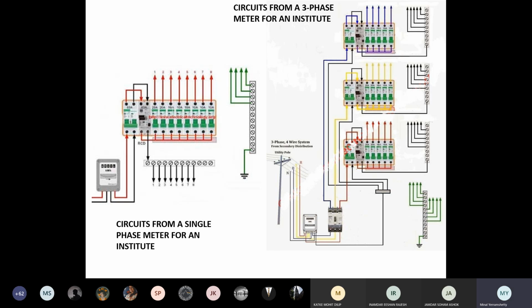So it goes to the main distribution box. And from the main distribution box, it gets distributed to bedroom 1, bedroom 2. One line will go to bedroom 1 and it will have an MCB. Another line will go to bedroom 2 and you will have another MCB. One will go to toilet 1, it will have one MCB. You go to toilet 2, it will have one MCB. You are getting my point.